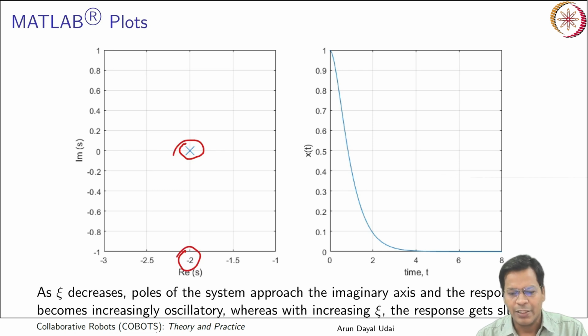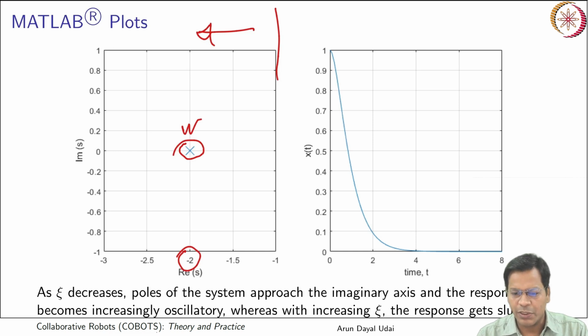So again it is on the left half side of your complex plane, both equal and real, and your system is critically damped. So you remember this: in this case both are real, on the left side in the complex plane, and your system is critically damped. Real and equal roots give you this case. This is the fastest non-oscillatory response.